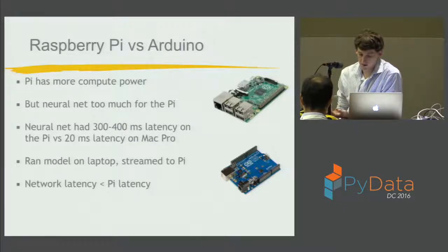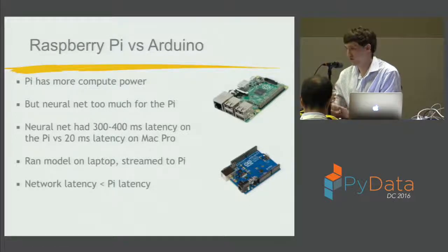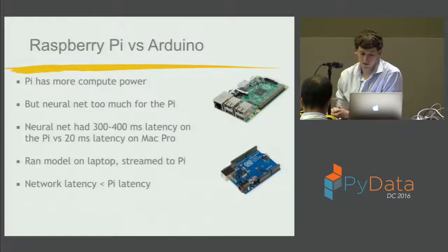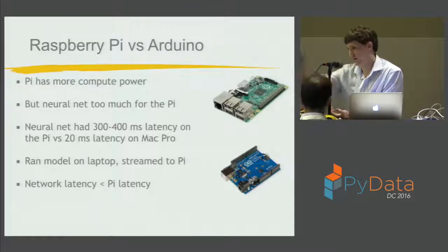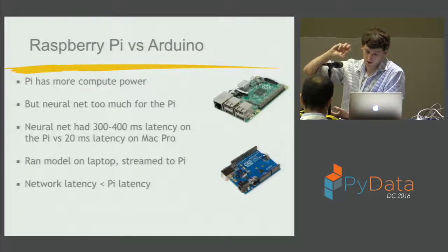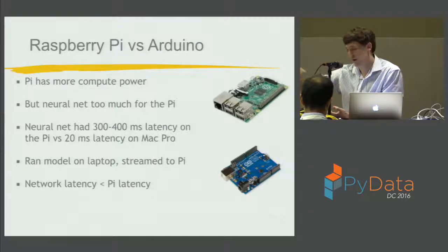And so I had some trade-offs. I originally wanted to have all of the machine learning done on the Pi so the car could react faster. I've deployed a lot of machine learning models in my work at Capital One, and latency is really important, and we try to minimize network hops. So I wanted to avoid sending data back and forth over the network to reduce latency, but it turns out that the latency hit from running on the Pi is substantially greater than the latency hit of just transferring these predictions and frames over the network. So I ultimately went with running the neural network on my laptop or on a server. I would get video frames from the Pi, send those over the network into my machine learning algorithm, which would ingest them and output the command back to the Pi, which would then interpret it and move the motors accordingly.